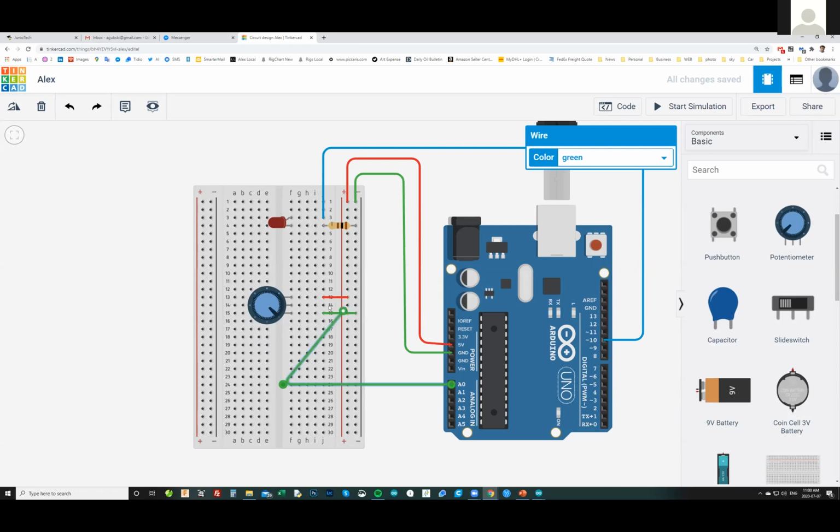Okay, so your wire is not supposed to be connected on this side. It's supposed to be connected on the other side of the gap. That's because your potentiometer has 2 legs here and another one sticking on the other side. Your potentiometer looks different from what's on the diagram. Your pins are not on the same side. There's a gap in between these 2 pins and the other, so you have to bring the wire from the second part, like on the diagram, okay?